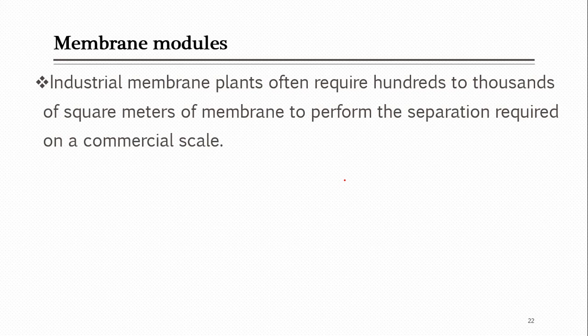There you remember we had 4 membrane modules or 4 parallel units running, and I told you that each of them has an area of 4000 square feet, and the overall required area was 16,000 square feet for that application.